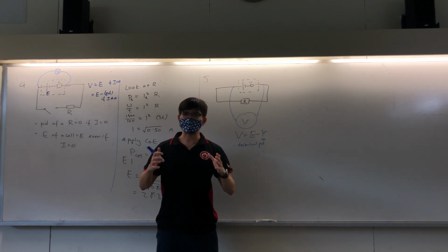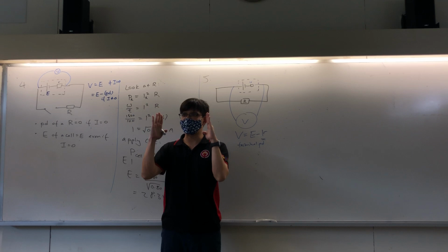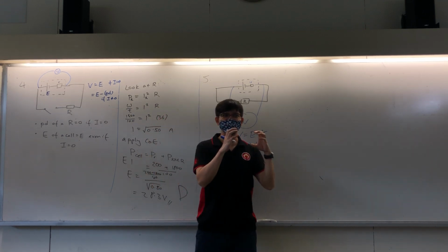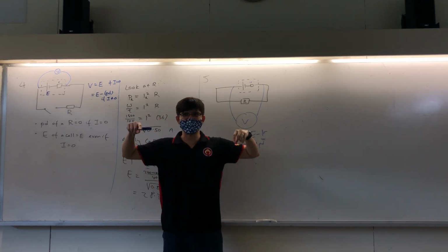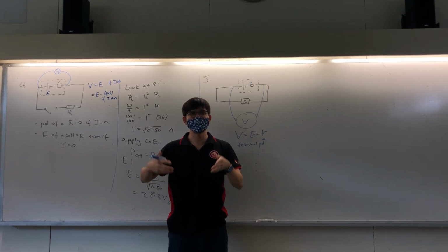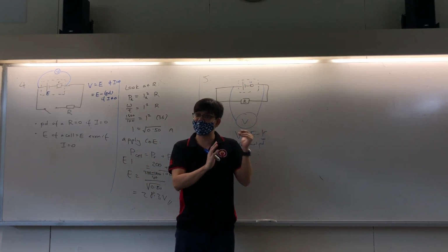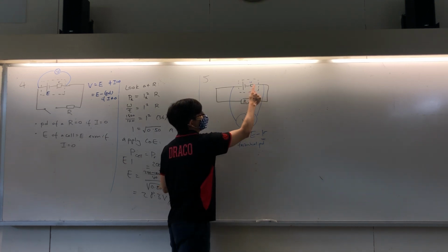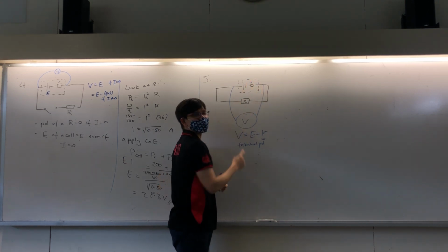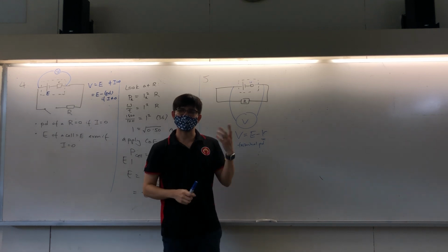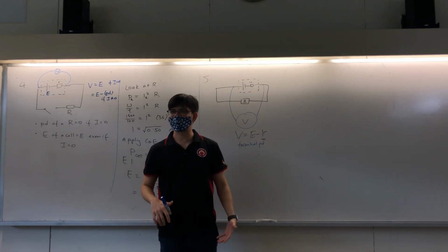Basically, there are two parts of your battery, the ideal EMF and the internal resistance. The PD that the battery can supply to the external circuit is whatever EMF you have minus whatever the internal resistance uses up. But the internal resistance will use up more if the current is higher, and the current will depend on the whole circuit resistance.